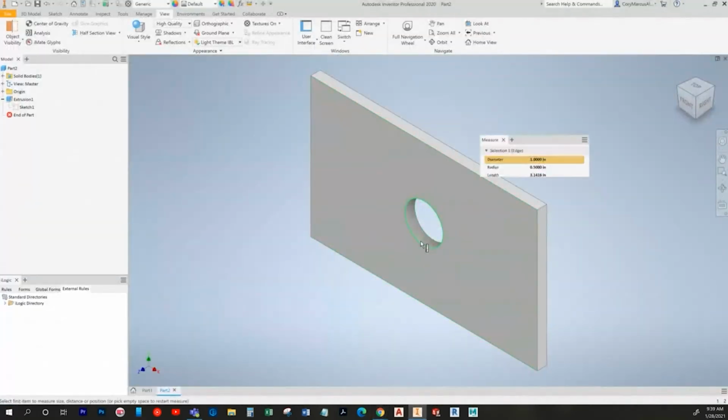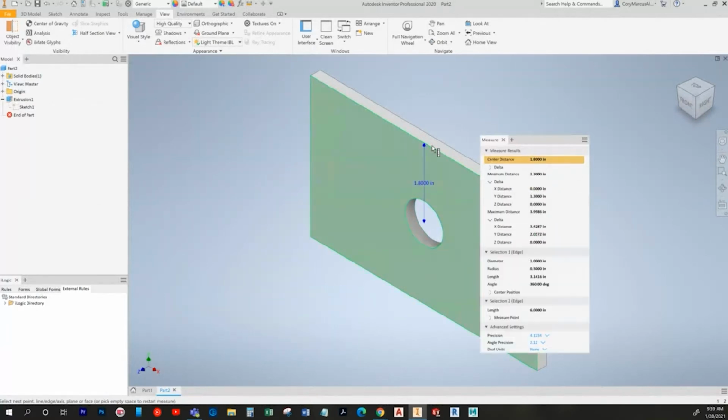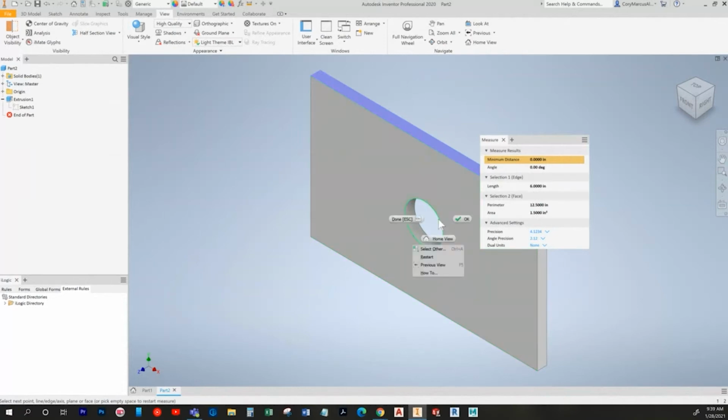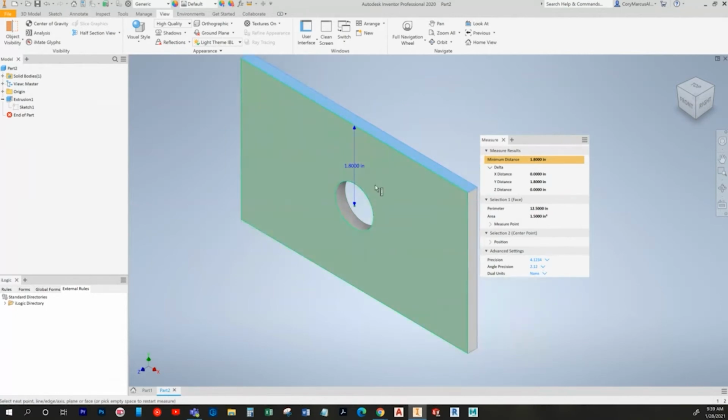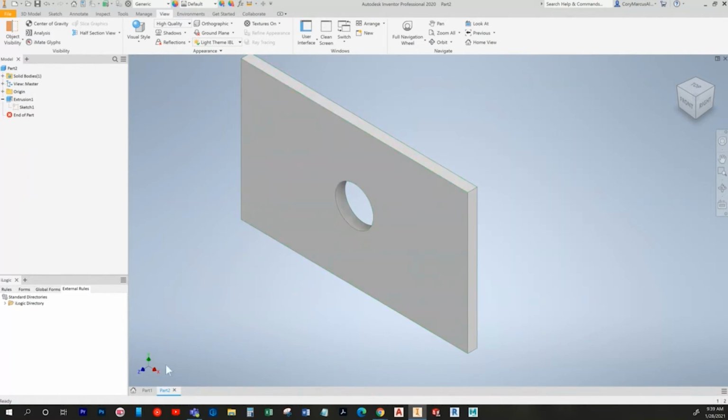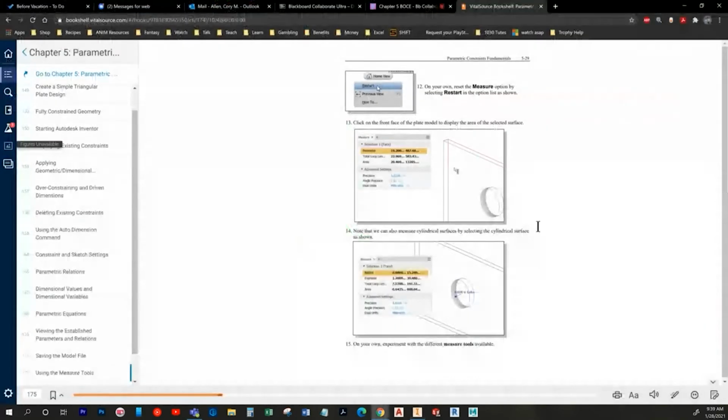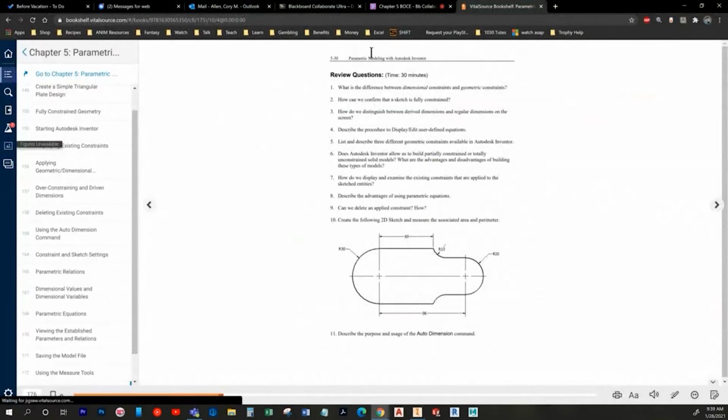And then with circles, it's kind of finicky. You've got to be careful to read the right information. It gives you both values, so say I go and measure to the center point here. Sometimes you may have a minimum distance that doesn't match. I didn't do it right in this case, but sometimes you really have to be cautious to make sure you're reading the delta option instead, because technically this distance to here may not be the same as the delta distance, which is going to be your XYZ in relation to your gizmo. So that's going to be it for this one, it looks like.